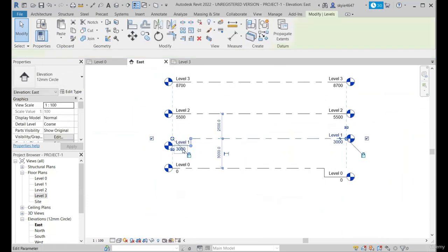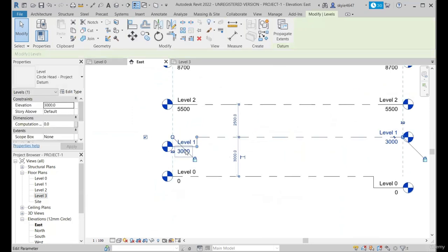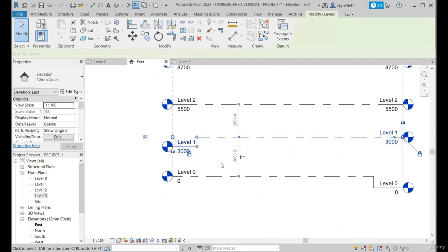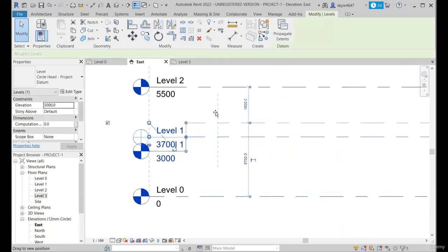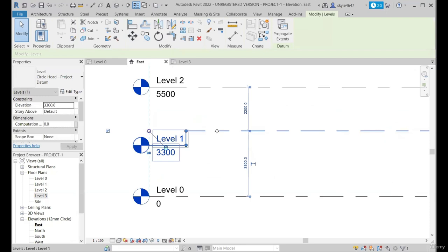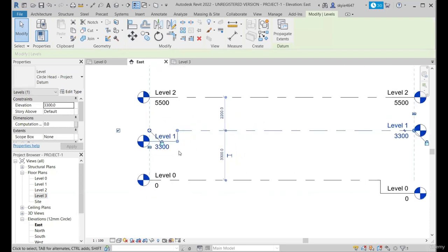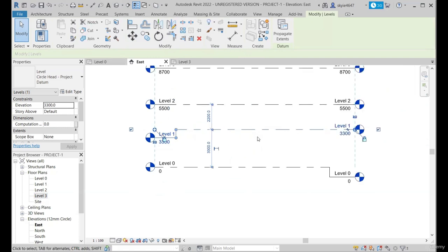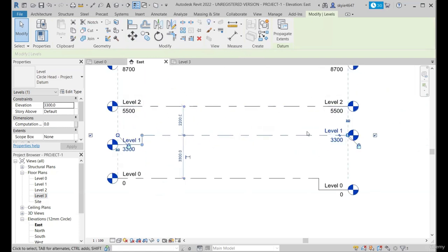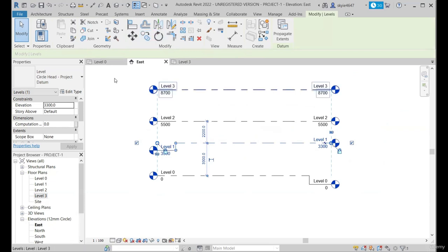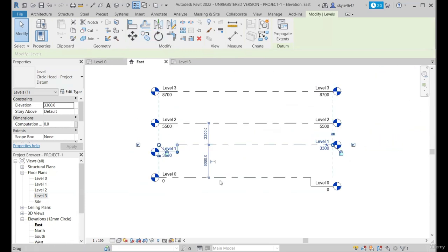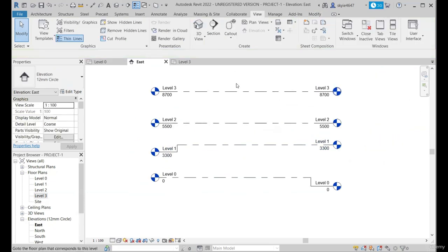Likewise, you can adjust. There won't be any change in level elevations unless you change it in the Elevation field under the properties, or you can move the levels if you want any change in the level. We'll take a look at all these tools in the upcoming sessions, but just to make sure we check everything that's associated with levels, I've just demonstrated a quick example. So that's it regarding levels.